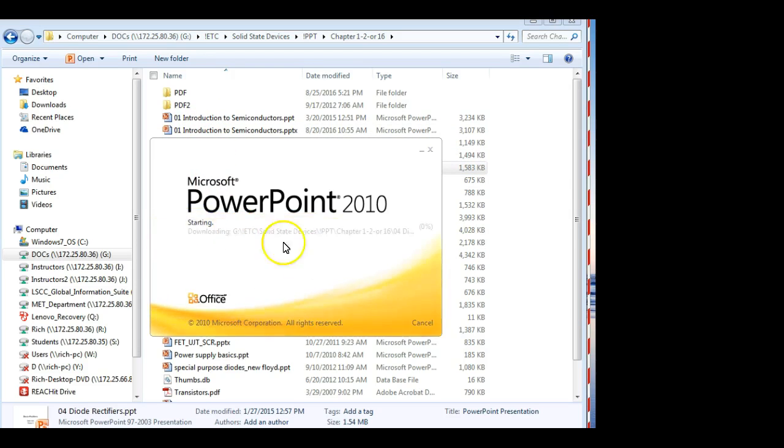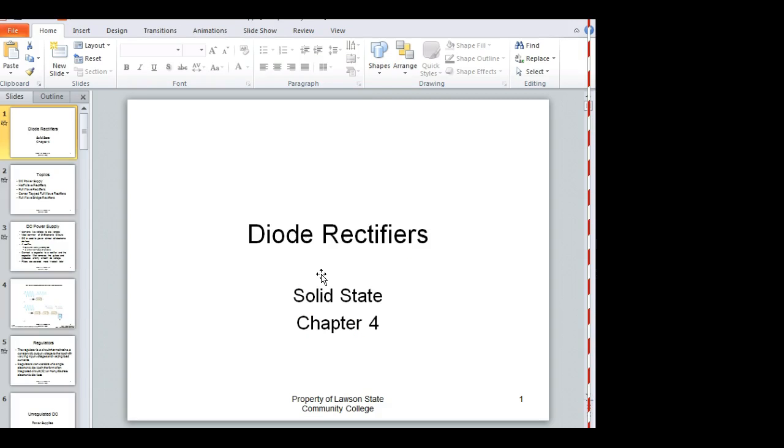Well, we need a magnetic field. It doesn't necessarily have to be a magnet. It can be an electromagnet. We need a magnetic field, we need a conductor, and we need motion. Well, AC produces everything we need.